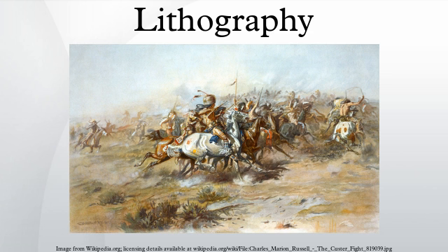In the early days of lithography, a smooth piece of limestone was used, from the ancient Greek word for stone. After the oil-based image was put on the surface, a solution of gum arabic and water was applied, the gum sticking only to the non-oily surface. During printing, water adhered to the gum arabic surfaces and avoided the oily parts, while the oily ink used for printing did the opposite. Lithography on limestone.